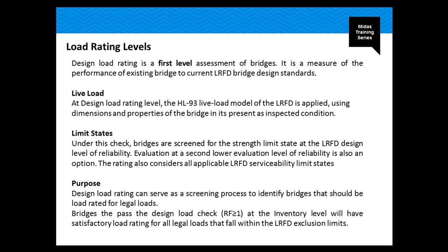The limit states in this case: the bridge is screened for the strength limit state as per LRFD. As you see, this one is very standardized as per the LRFD bridge design standards. The evaluation at a second level of reliability is also an option for this first level load rating, and the rating also considers all applicable LRFD serviceability limit states. This can serve as a screening process to identify bridges that should be load rated for legal loads, that should be evaluated basically.